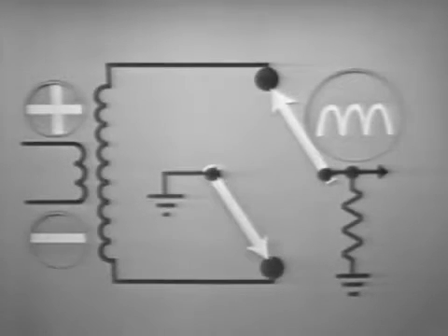Now let's go a step further and discuss the voltages present in the circuit. Remember, earlier we stated that if you understood the principle on which the bridge rectifier operates, you'd have no trouble calculating any voltage in the circuit. Now, I'd like to show you exactly why. With the load always connected to the positive end of the secondary, and ground always connected to the negative end, couldn't we simplify this and say that the load is always in parallel with the secondary?